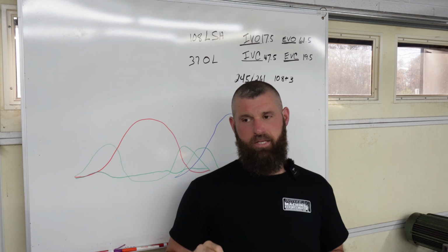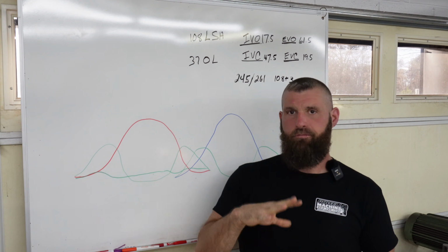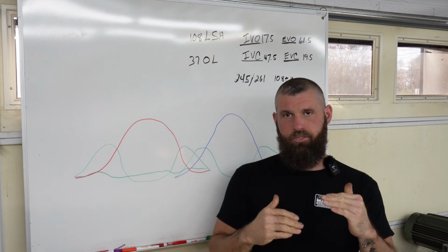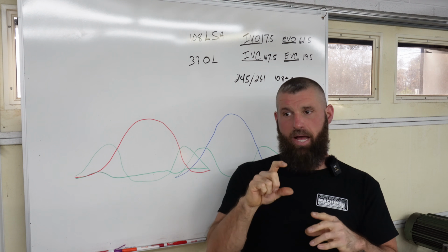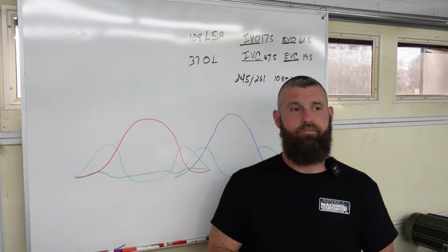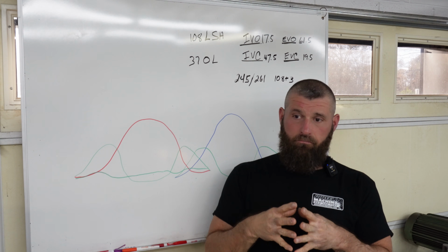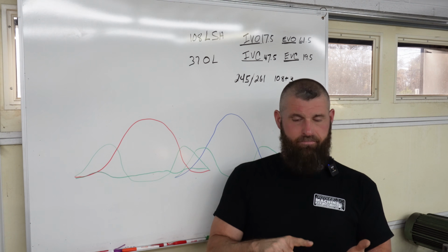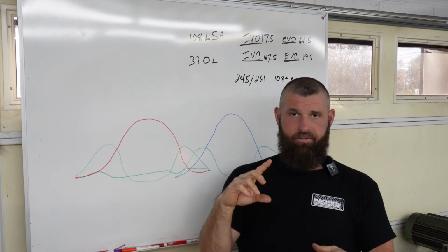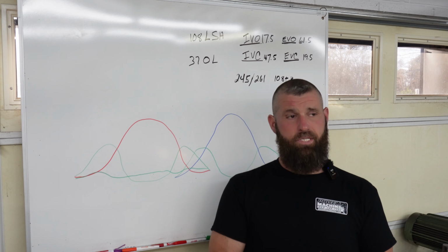So now I've come up with a way to log all of the design parameters for each family. I built basically a spreadsheet, so I have all of that data logged. When I go back to make another lobe for that family, we have all of that data in place. That way, each family is going to have the same opening and closing derivatives, the same peak acceleration, and the same hydraulic intensity or mechanical intensity, depending on if it's hydraulic or solid.